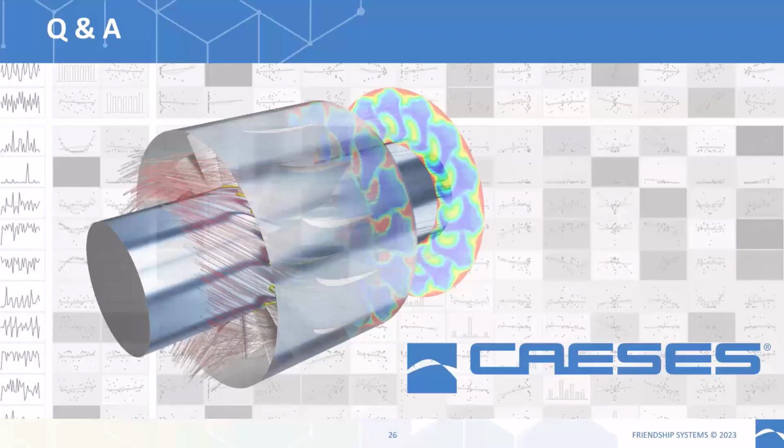So you can either use these templates and then modify them to your liking, or you can also define completely custom definitions. So if you don't want to use a meridional contour or an airfoil definition that you see there in the given library, you can just simply use your own one, and you can use feature definitions to write your own airfoil definitions and so on.